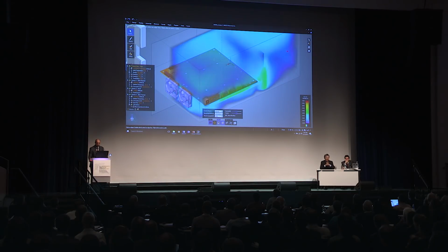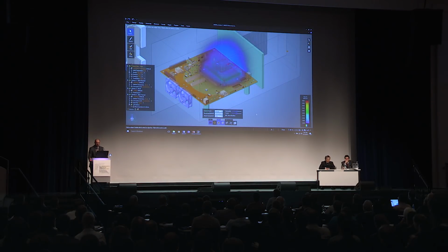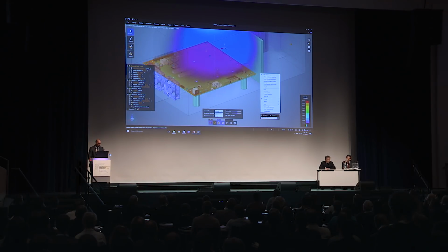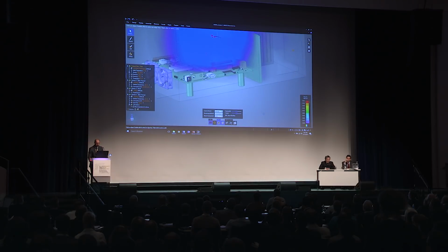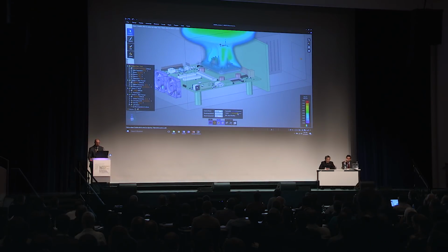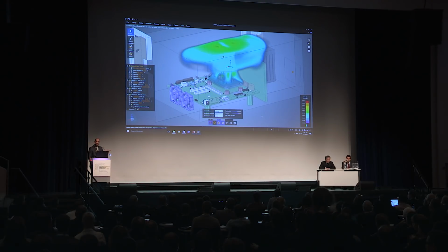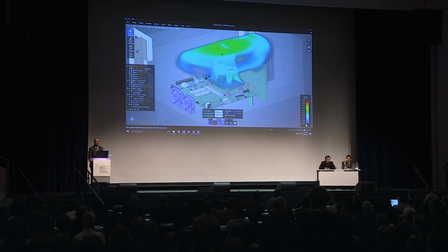And we'll change to a composite display. So what you're now viewing is the heat moving through the volume and rising in the enclosure. Check that out. From the heatsink that we just made, that we just designed. And maybe we could go even a little bit farther.